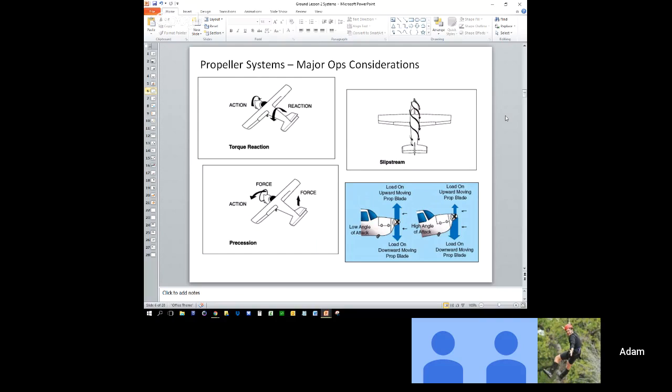At 2,200, you'll kind of notice it, and at 2,000, you'll hardly notice it. So it's probably not linear. And your second question, for multi-engine aircraft, in later design engines, propellers actually spin opposite each other to cancel out some of these effects.